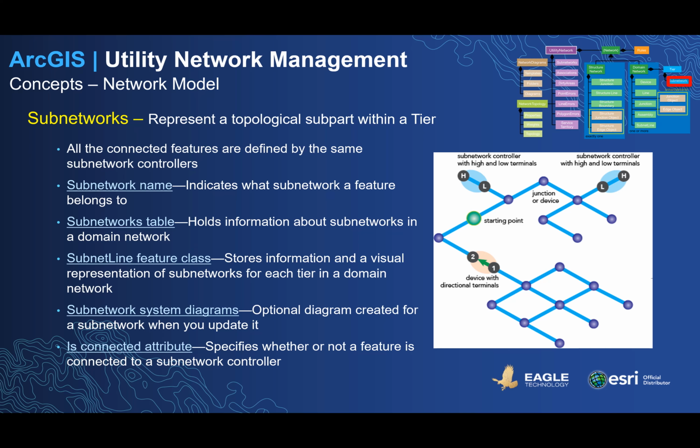The subnetwork line we talked about a few slides ago is created by a trace task on a valid network topology with no errors. The update subnetworks task then stores the roll-up of your network property on an aggregated line feature, which you're able to represent to your users in their maps so they're able to run traces. This would generally happen after all of your edits are posted and validated as a manual task, or you can script it to run as a maintenance task by an admin.